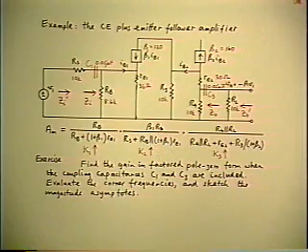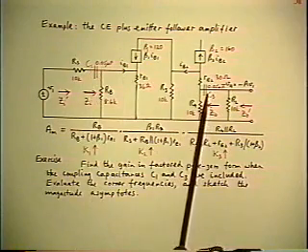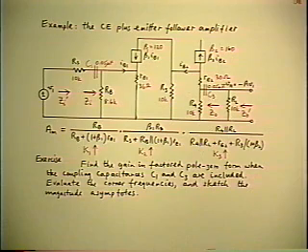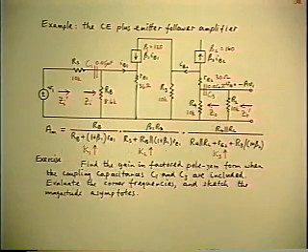So without stopping for that diversion, let's go back to this case and do one more, which I'll also leave for you to do later. And that is, let's forget about the C2, and instead, let's put the two coupling capacitors in. The C1 at the front end, C3 at the back end. So once again, we can practice the extra element theorem to find the modified gain expression to account for the C1 and the C3.